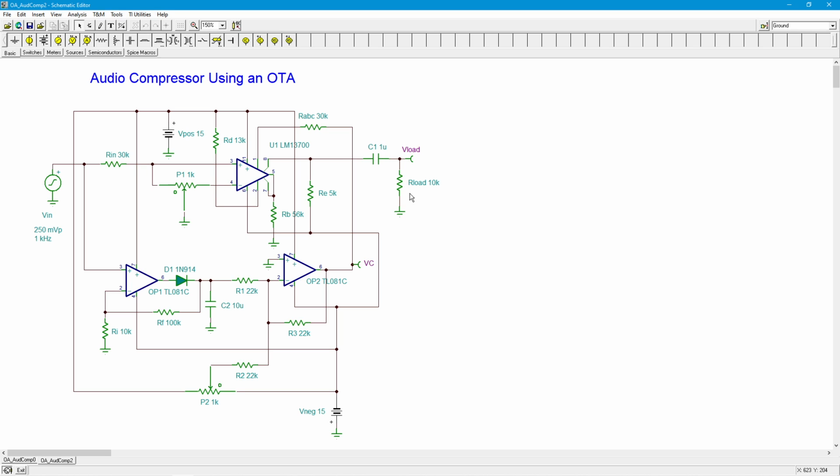And we just want to see what the gains are going to be as I change this input. What do we see at the output? By the way, if you're wondering about P1, I'll just remind you, P1 is there. You can tweak that to adjust a little DC offset that you might get at the output. In our output, since I've just set this up for 50%, I left it in there just as a reminder for those of you that might be breadboarding this. We are going to see a small DC offset at the output. Don't worry about it. Anyway, let's see what we get.